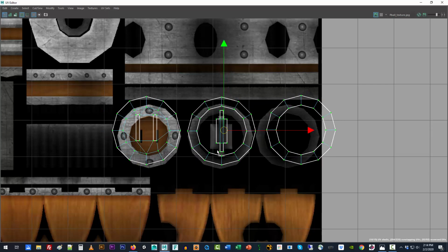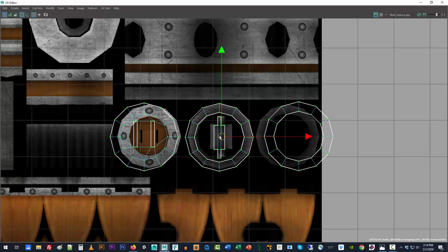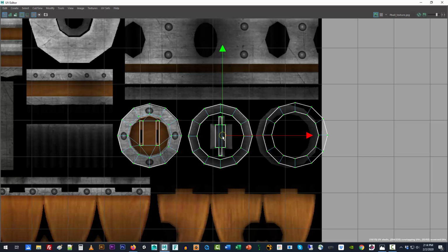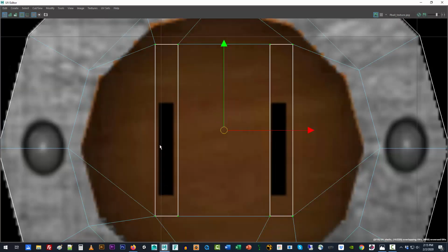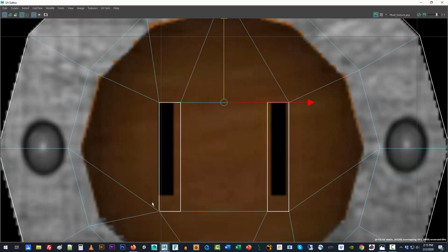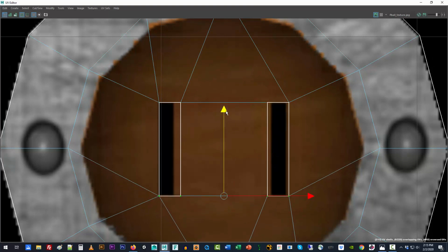Now what I'm focusing on is this middle ring, and I want to grab everything uniformly again, because I don't want to fix all things at once. I want to just take care of one aspect of these at a time. These seem to have lined up pretty well. That's kind of cool. And if I wanted to further modify it, I could come in here and grab these UVs and make sure they align perfectly with the holes, like so. And it may be better if I don't do it uniformly, but if I grab them and actually translate them down, then I can start hitting exact points and not doing it UV by UV.